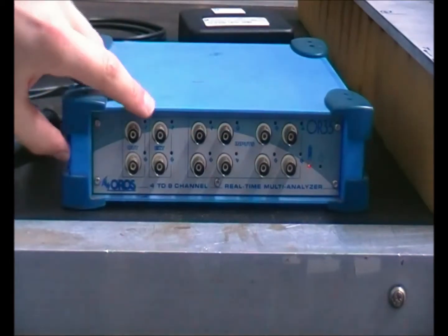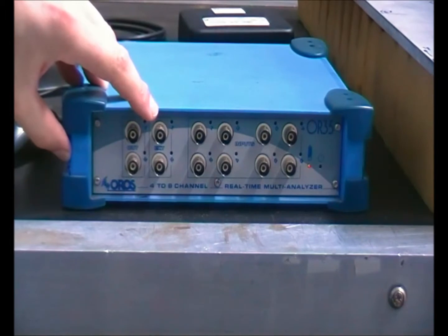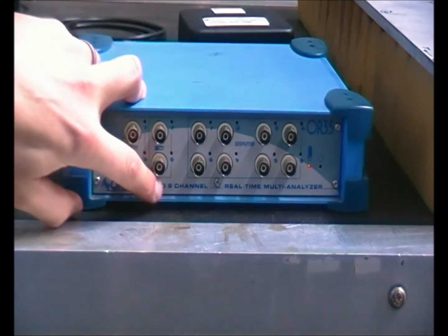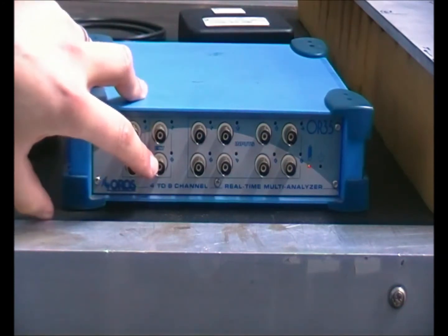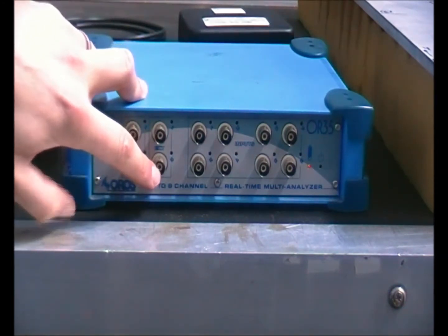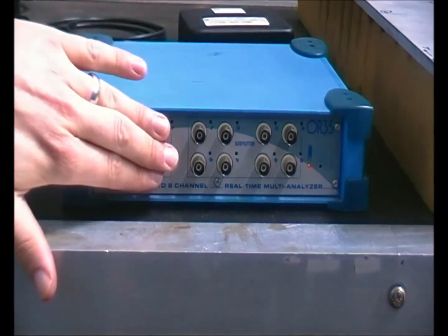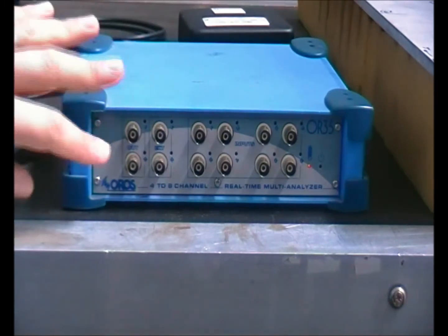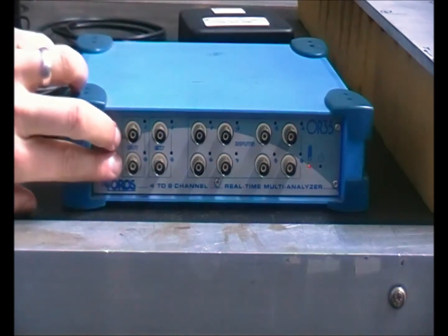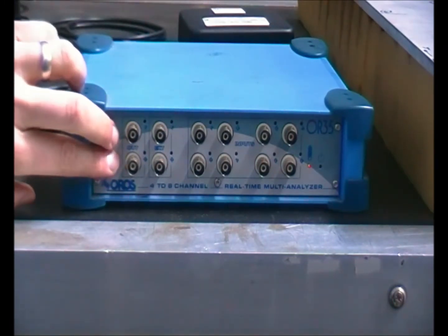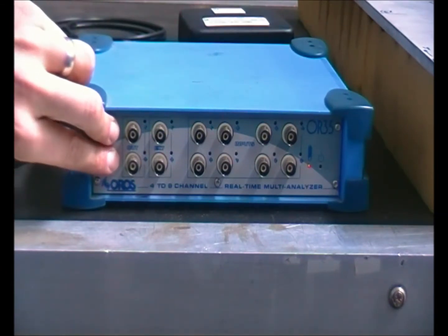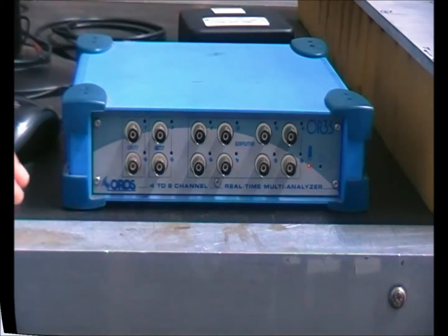We've got 2 external inputs that are basically digital input channels, very useful for triggering and if you use something like a tachometer and shaft encoder on a rotor. But this is typically what you would use in the OROS NVGate software, which I'm not going to focus on today. And then we also have 2 output channels that you can use to drive electrodynamic actuators, for example.